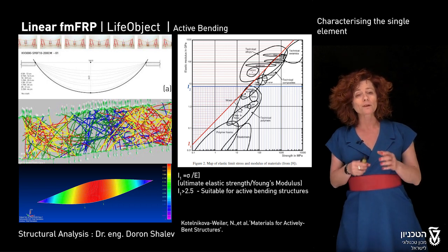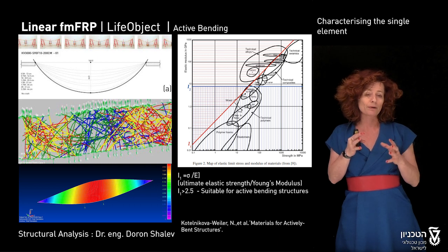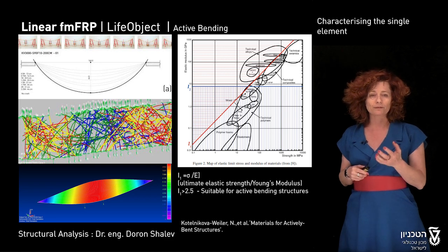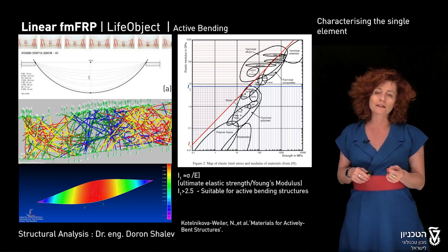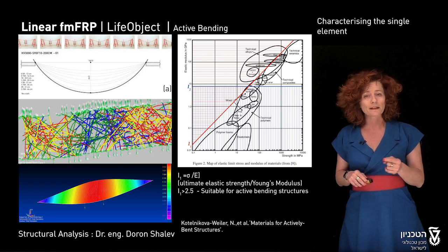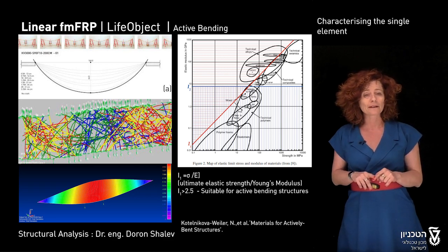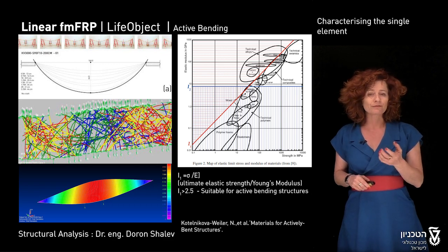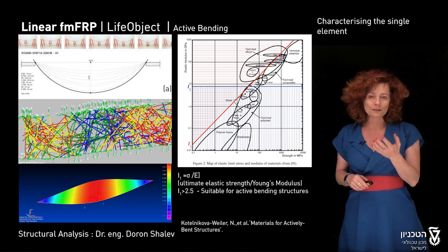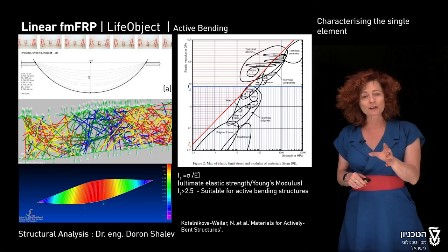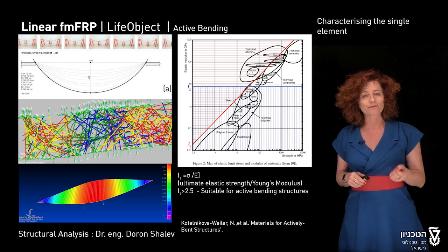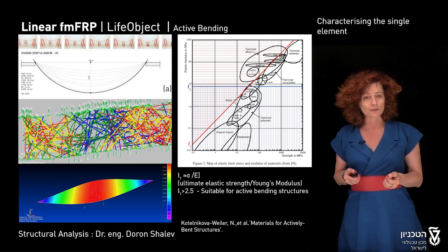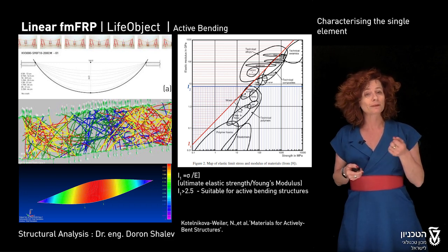In our case, it was not only the bent shape or the double curved shape of the overall element, but also its structural performance. The stability and stiffness of our structure is achieved by the interaction between these elements in active bending, applying mutual forces and friction, one element on the other, and together forming this stable structure. Based on previous research, we could learn what the requirements are for this kind of material that could be at the same time resistant enough, but also flexible enough not to break, not to bring us into failure.